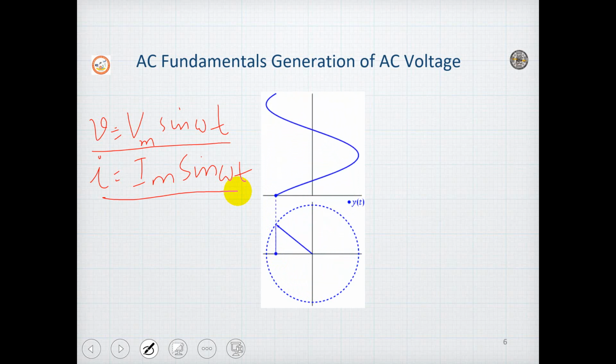So, the advantages of this purely sinusoidal waveform. In a sinusoidal wave, even after repeated differentiation or integration, it remains a sinusoidal of the same frequency. That is the first advantage. Second advantage, applying sinusoidal voltage to properly designed coils results in a revolving magnetic field which is capable of doing work. So the majority of electric motors used in commercial and industrial applications work on this principle.